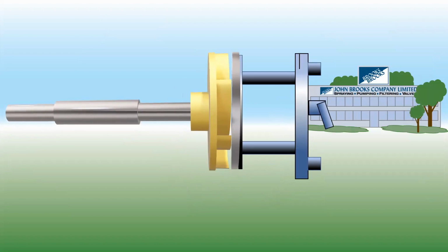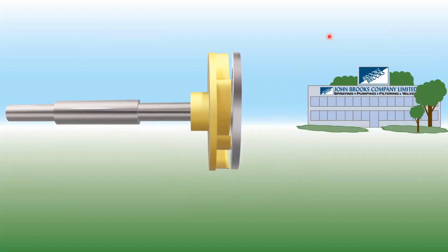So essentially, when this gap opens up, what we're going to get is recirculation. High pressure from the tips of the impeller vane will push the liquid not out the pump casing itself, but to recirculate into the suction. And that's not a good thing. We have a pump because we want to move liquid. We don't want to mix the liquid. So this becomes very inefficient.